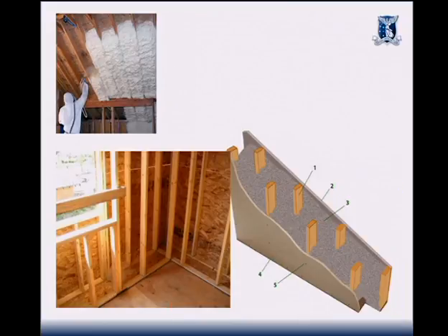So, double stud wall. Try and walk onto a site or talk to a client who's building their dream house and say, I'm going to more than double the thickness of your walls at increased cost, reduced floor area, added labour and all of that. And they say, why are we doing this? And you'll say, oh, you'll pay $200 for heating instead of $300. So that is literally the problem that drives the fact that people don't tend to do this sort of construction.